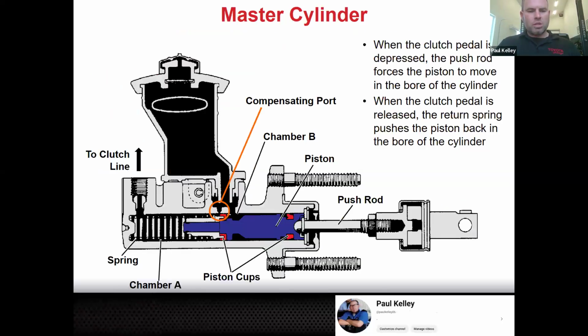Cool. And then this shows a little bit more detail of the master cylinder. Here's that beautiful push rod adjustment. Loosen the nut and spin that rod. If you turn it up from this perspective, that's going to lengthen it. If you turn it down, it threads in here and that's going to shorten it. You would just be wiggling the pedal as you do that, checking the free play.